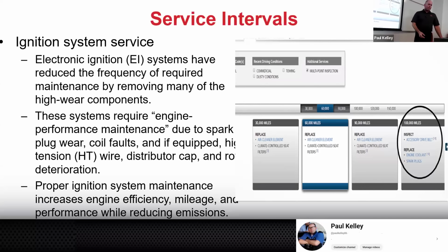So back in the day, they might call for that at 12,000 miles or 12 months. So every year, you're going to get a whole bunch of ignition parts thrown on the car. The parts were cheaper, but everything was cheaper back then. It wasn't real efficient, right? Then as they went to a little bit higher quality and got rid of the points and the condenser, maybe it's a distributor ignition system but with no points, that might be like 24,000.